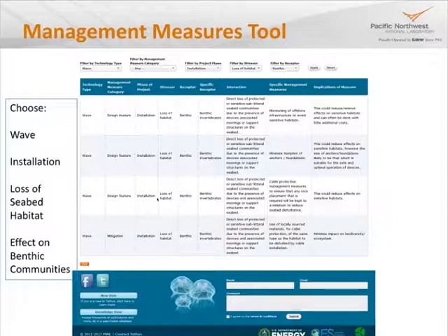that had to do a good deal with how you avoid this loss of habitat. The first one is obviously micrositing, careful siting to avoid rare habitats, particularly, let's say you're in a very large soft bottom habitat area with some small amounts of hard habitat, reefs, say, you would want to avoid those. And again, this is something that can be done right up front in siting. Again, when siting and organizing the actual installation, the second management measure is simply minimizing the footprint of anchors and foundations. And this obviously, again, creates less loss of habitat.